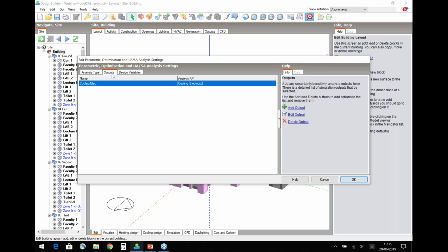For example, if U value of the wall is changed by using different materials, then the wall option sequence, when ordered in decreasing U value, might not correspond with the one created with increasing capital cost. In those cases, sensitivity analysis must be done separately. While theoretically sensitivity analysis could be done for both objectives together, it is generally a good practice to set them up separately.